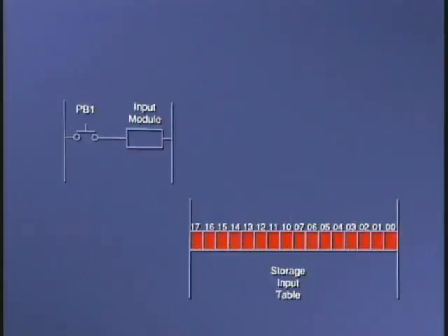The field status information of on or off, open or closed, provided by the standard input module to the processor, regardless of signal level or rating, is placed into a 1 or 0 in the input table every time the processor reads the input. Each input address has an input table location where it's mapped. These locations are examined during the execution of the program, or during the program scan, to determine whether or not a PLC instruction would be providing power continuity in the control ladder program.